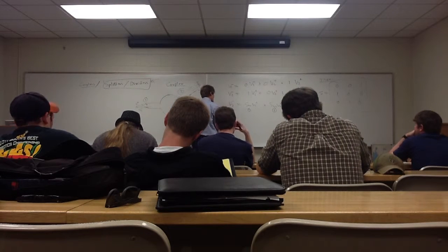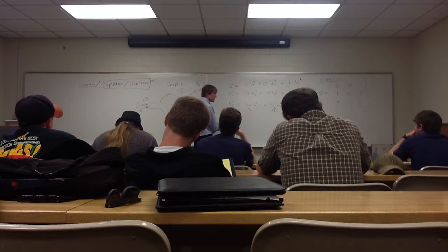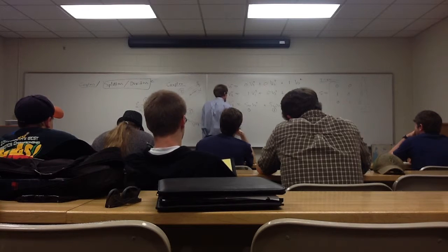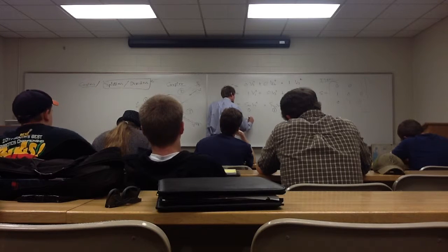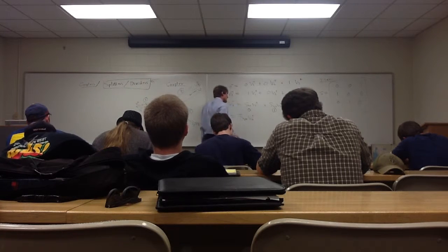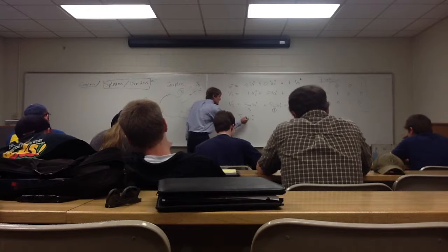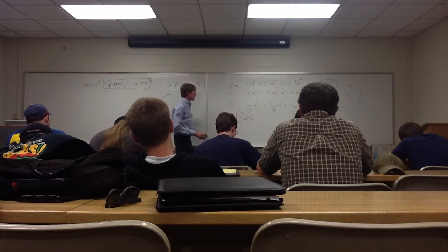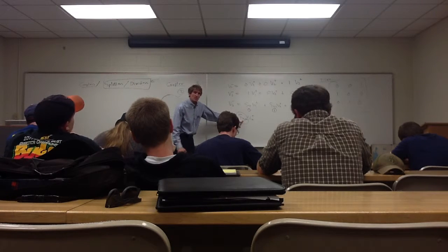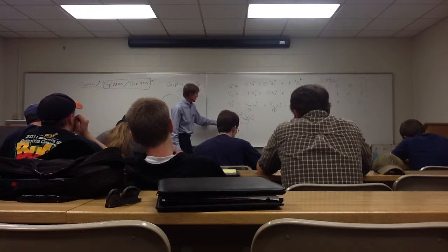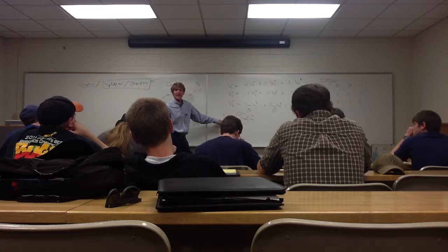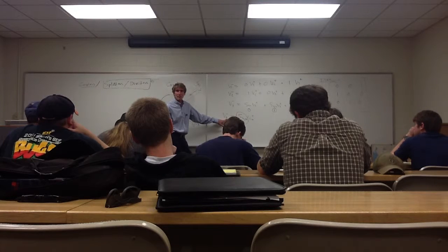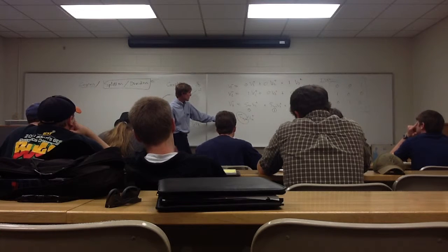Whenever you want some V of n minus, it's going to be equal to some S of n comma m times V of m plus. This is the S parameter that couples it. If you want it to be 0, n can be anywhere from 1 till 100, or any number of ports, but really we'll limit it to 1 to 4, really 1 to 3 for the test.